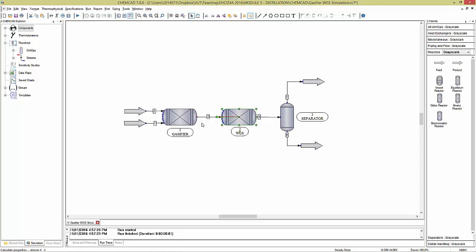That heat exchanger is going to use cooling water. I would need to see the flows of the cooling water, the flows of the utilities. That's what your flow sheet needs to look like. This one, I'm just guiding you through the flow sheet synthesis. For your flow sheet, you need to specify everything.